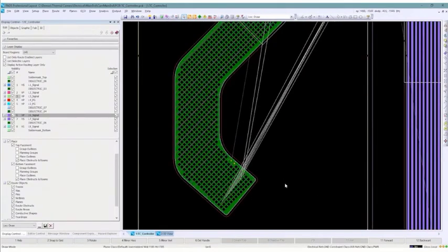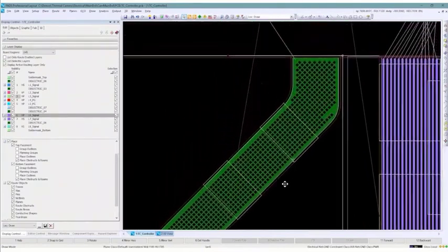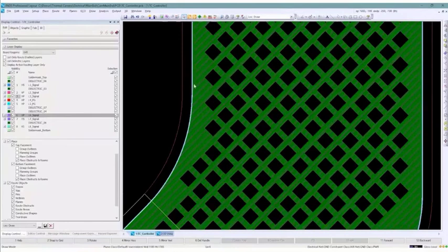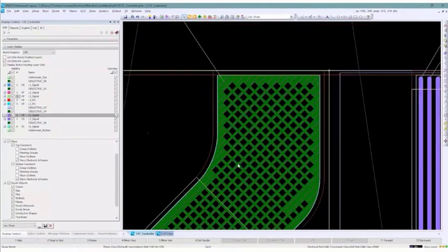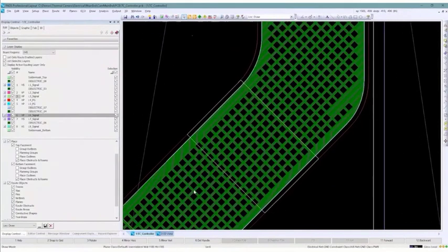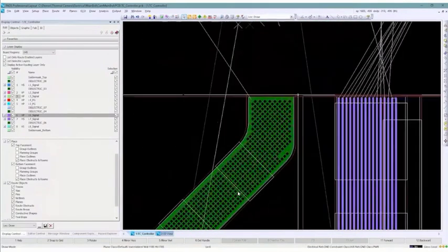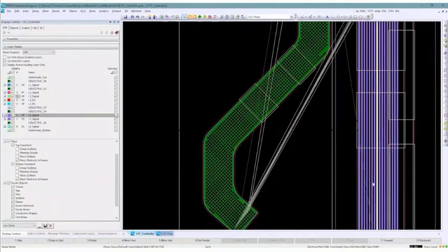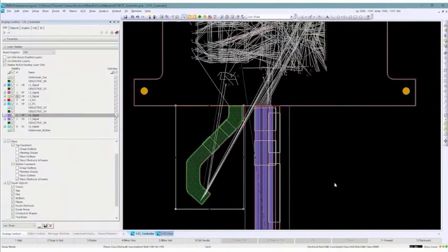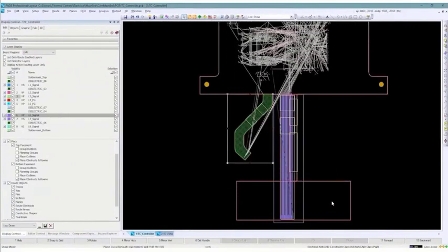It's only going to fill in the copper inside of the board outline, or the route border, I should say. That's one of the handy features of the route border, and it's hatched based on my requirements. And for each one of my plane areas, I could go in and specify something completely different, or each area on the board, even for that matter. So my little button board up here, I could have something completely different than each one of these flex as necessary.